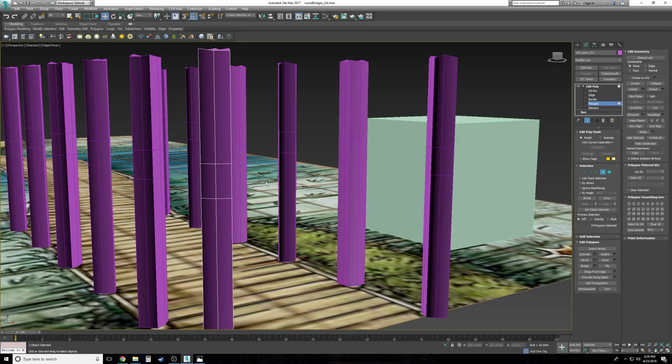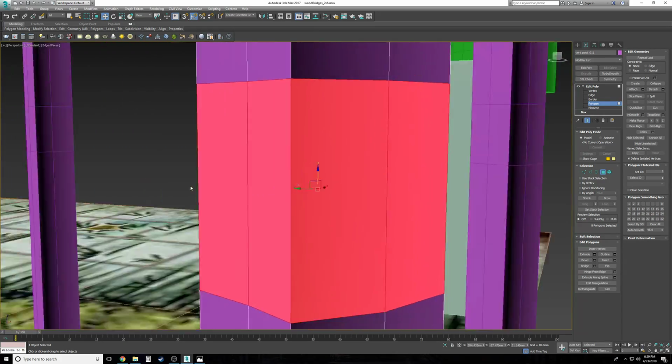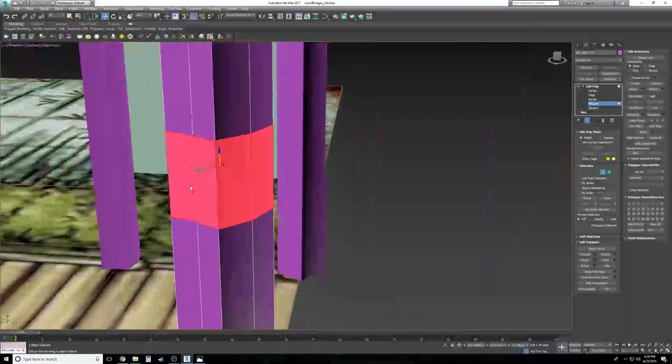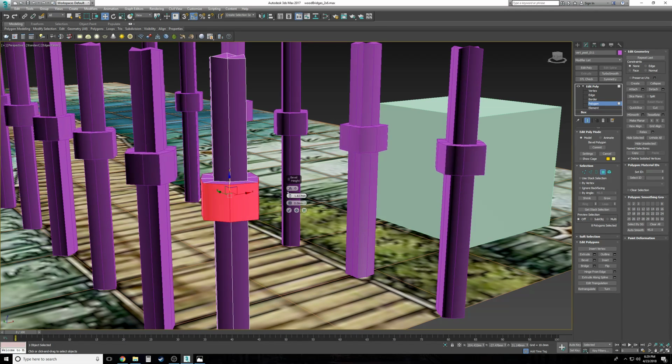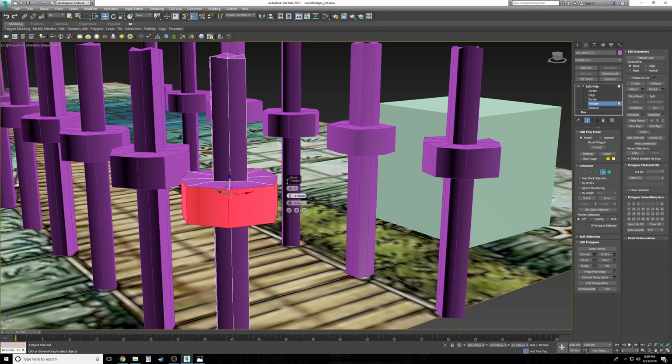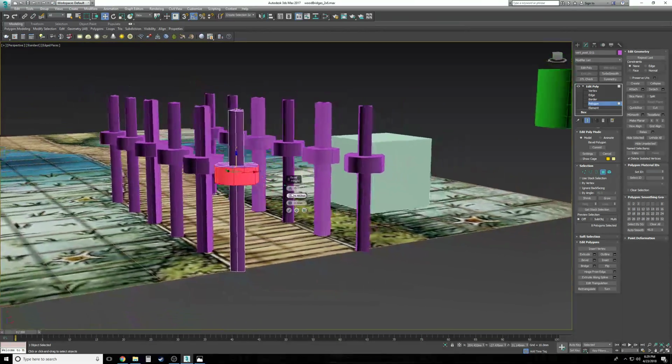I'm going to take the polygon. Let's select it so that just that area is selected. You follow me? You see what's coming? We're going to go to bevel. We've done this before. Go to bevel, change the group to local so that it comes around the central axis. And then we're going to extrude first. Oh, baby. You see what's happening? You see what's happening?